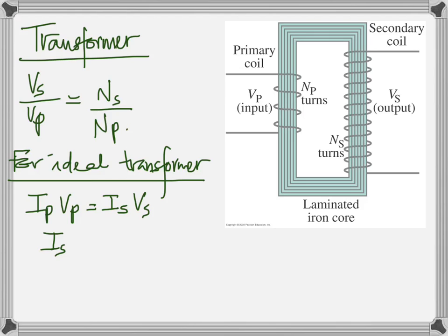So there's going to be heating losses, number one. There's going to be magnetic flux losses. That's what I'm talking about. Magnetic flux losses, number two. And there's going to be what is called hysteresis losses. I'll explain that later. Magnetic hysteresis. Okay, it's not hysteria. It's closely connected. And number four, if you watch very carefully, you see that the core, which I told you is made of iron, is not a block of iron.